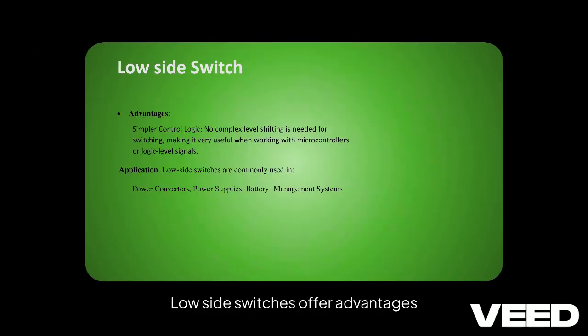Low-side switches offer advantages like simpler control logic, as no complex level shifting is needed. This makes them ideal for use with microcontrollers and logic-level signals. Applications include power converters, power supplies, and battery management systems.